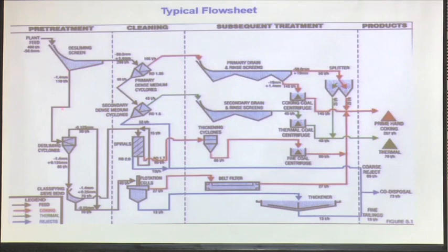So in pre-treatment, you see that there are basically different sizes. You have got a disliming screen. What does a disliming screen mean? If I have clay materials, ultra fine materials, below 150 micron, below 45 micron particles, then what will happen? Because I am using a fluid medium, that will change my viscosity, that will create viscosity related problems, and my slurry rheology will be different.